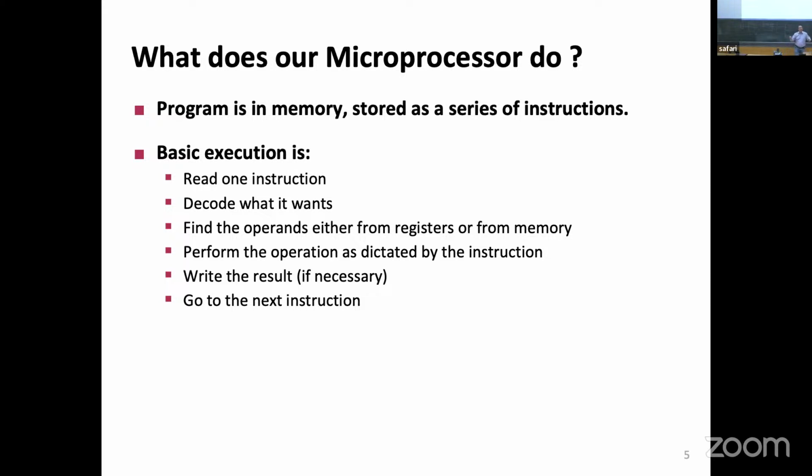Well, if it's an R-type, register-type operation, I have chosen the first register, I've chosen the second register, I got those 2. I went into this ALU, and some part of this instruction, secretly, told me what type of operation I should be doing, or function.